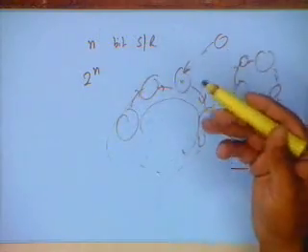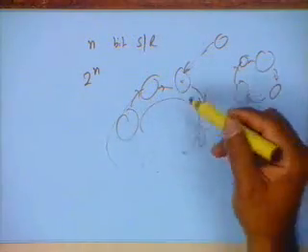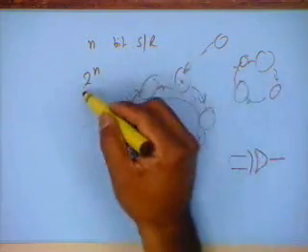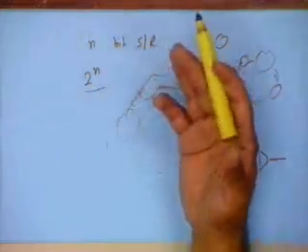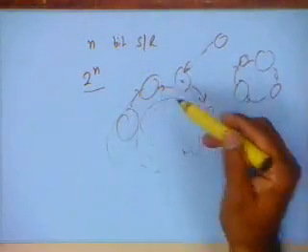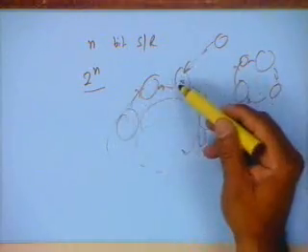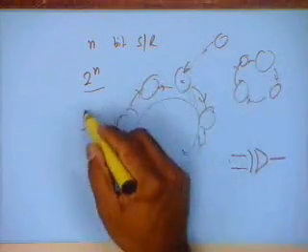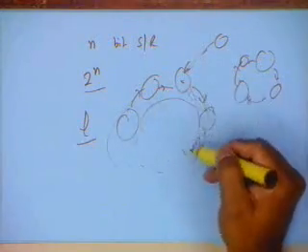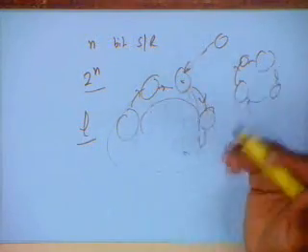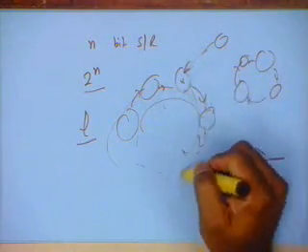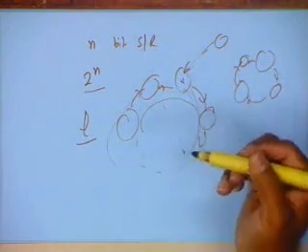So you have to start from a good seed, and this can actually be designed. There are techniques available, and you can also design it, try it out, and make sure that starting from a seed I get a fairly large pattern. It may not be the full 2 raised power n, but even if it is close to that or of the same order, it is good enough. Out of this I may not use the whole 2 raised power n, whatever the length L is, which is close to 2 raised power n. I may use only some fraction of it for my testing purposes. And each time I will start from a seed, and then I will go through that particular pattern.